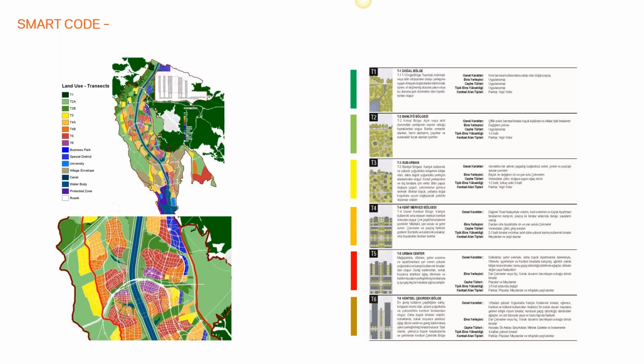That's not exclusive to HOK. It's actually quite a common planning tool nowadays. But what it essentially does is, instead of defining zones as far as what can be commercial, what can be residential and what can be industrial, it defines the kind of feel of the area. So a T1 would be completely natural and untouched. T2 is more rural. T3 gets into suburban, and T4 and T5 we get into some more mixed use and urban areas, and then T6 you could think of as the core, the high-rise city center.